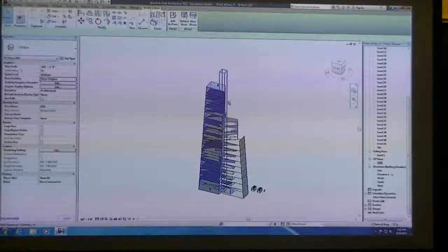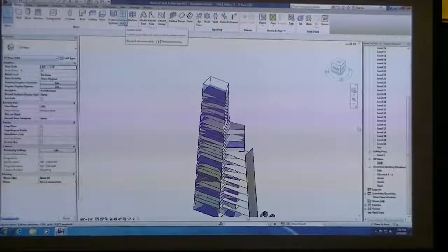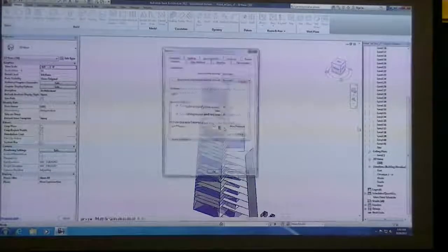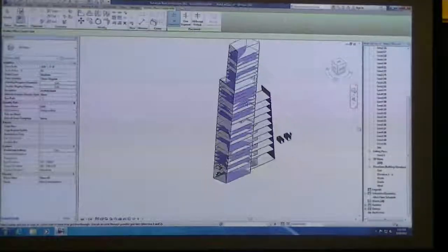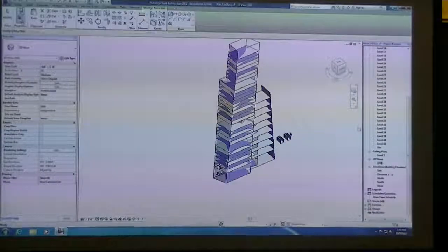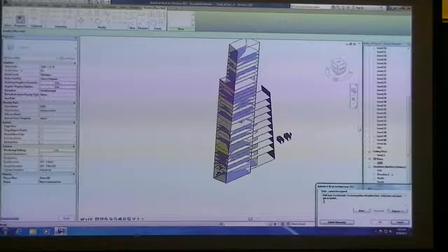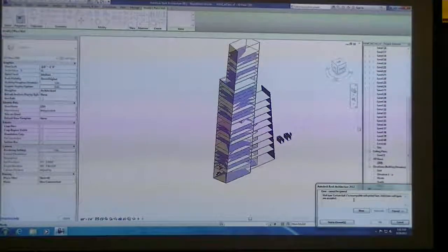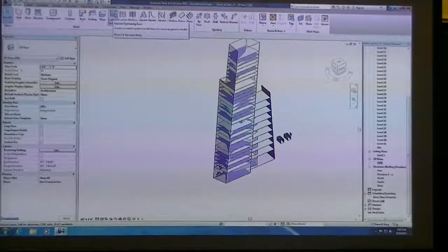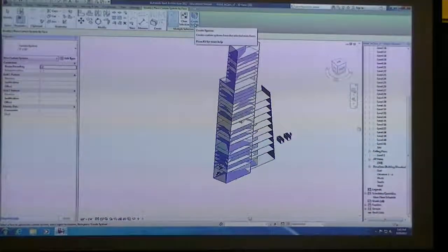Another method for working with the exterior would be, since you have a curtain component, if you try to apply a curtain grid to a curving face, or slanted or whatever, click on wall, curtain wall, and then I apply and pick face, it's going to yell at you and say, well, we can't make a curtain wall because this tool needs to be something that's straight up and down. So it's not going to like it, and it's going to make you delete the element, or you obviously just cancel. So if you use a curtain system, you can select a face, and when you're done, create the system.